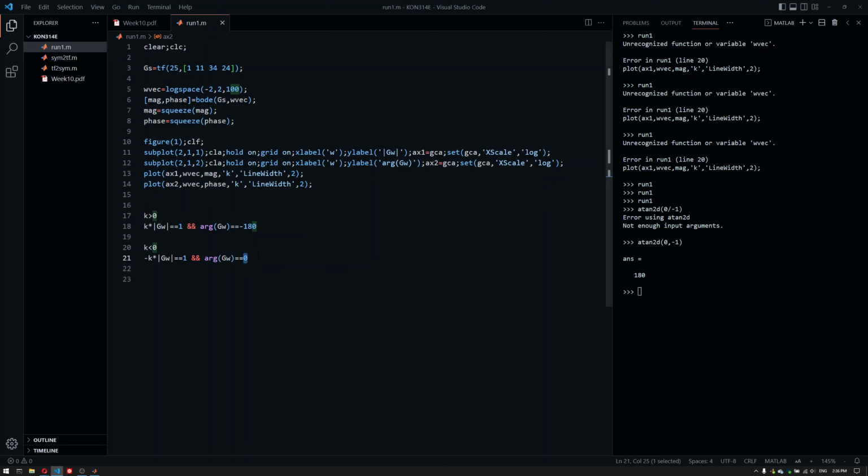The nice thing about this, about the stability and the Bode plot, is that we can basically use the system on its own, use the Bode plot of the system, look up the negative 180 degrees and 0 phase values, and come up with the frequency value, so omega star, the corresponding frequency that we're interested in.